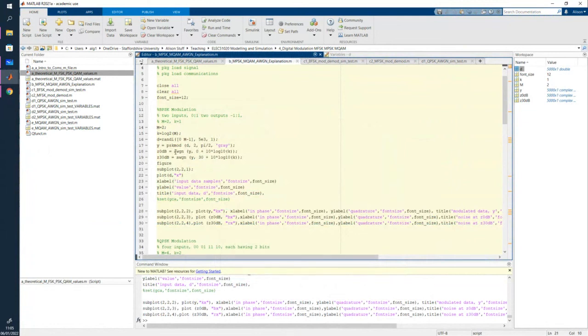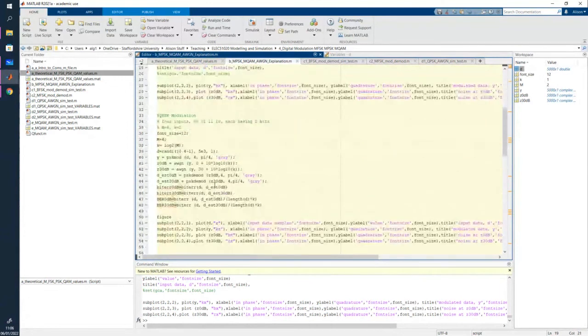So for the additive white Gaussian noise function, we just say the input signal, which is Y because it's being modulated, and then we add the noise plus the log. To get the right theoretical value, we need to match the value of M, and I'm not going to explain that here because that's too complex, but take this as correct. We could do the same thing for QPSK modulation.